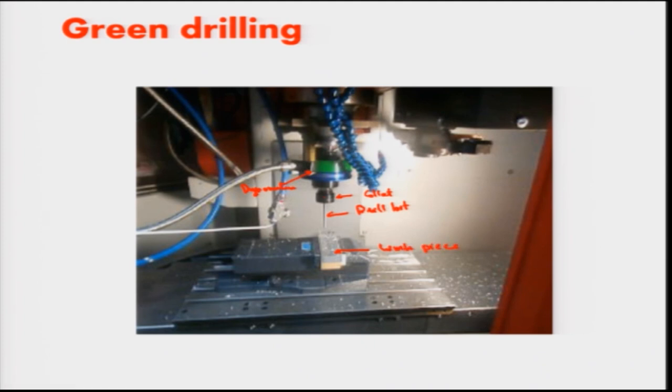What is this component? This is a nozzle that is throwing mist on the workpiece to cool. There are certain methods to cool the workpiece or the tool while we do machining. One is flood cooling. We provide a flood of the fluid and that cools. But in that case, the coolant is recycled, but a lot of coolant is consumed.